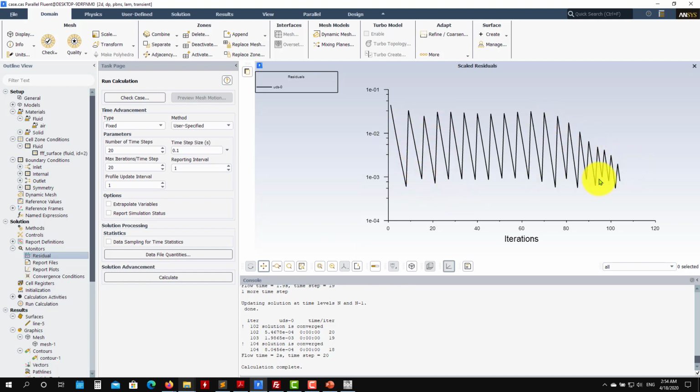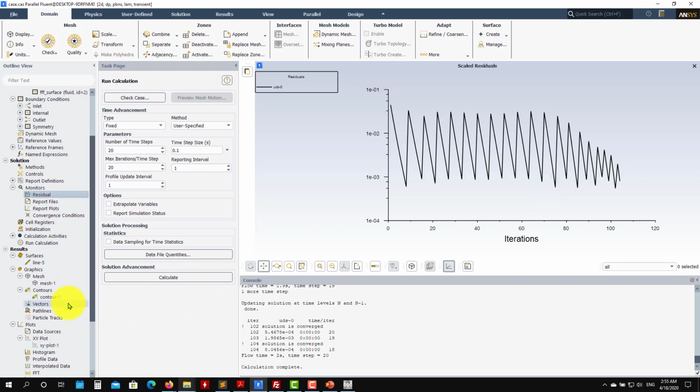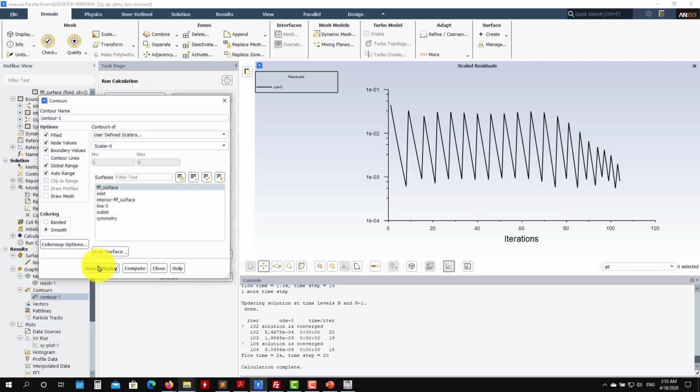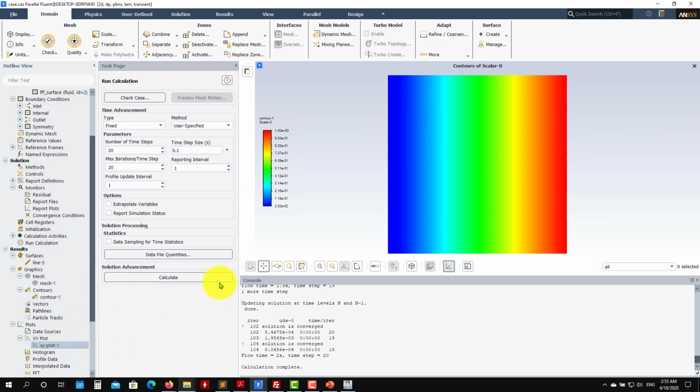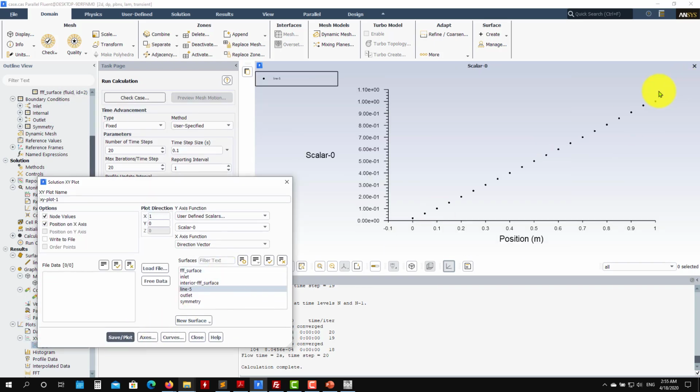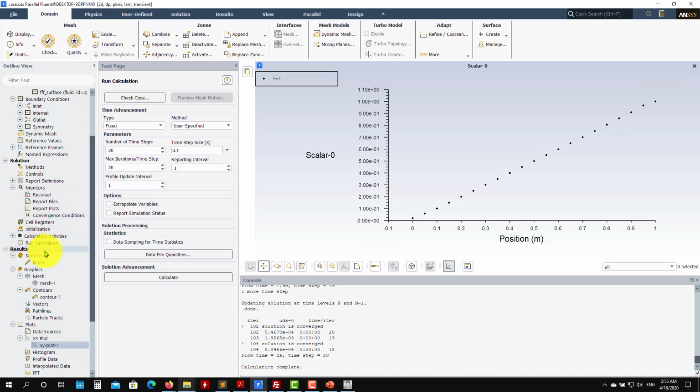And as you see this behavior, that your initial residuals go to your final residual, means that you are reaching a steady solution. And let's visualize what we have. Okay, if I plot the solution again here, you see that this one is iterating more than the steady. It's doing, besides outer iterations, inner iterations, so these solvers are more time consuming.